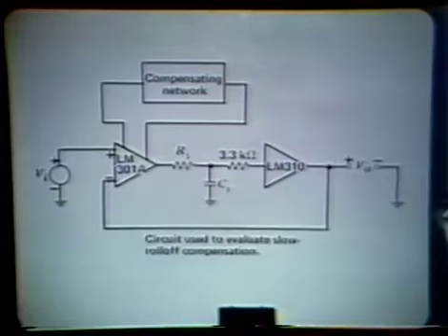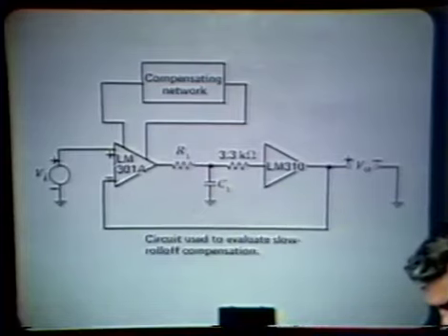And what we're going to do is attempt to come up with a compensation where we maintain adequate stability over a very wide range of R1, C1 products. The difficulty, of course, is that if we use a single pole compensation with a fixed value of capacitor, certain values of the R1, C1 product will cause us to cross over in a 1 over S squared region. In fact, it's certainly possible to have very, very long regions of 1 over S squared roll-off with appropriate choices of the R1, C1 product. And so we can get very, very low phase margins in that sort of a system.